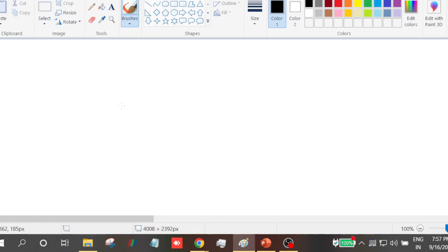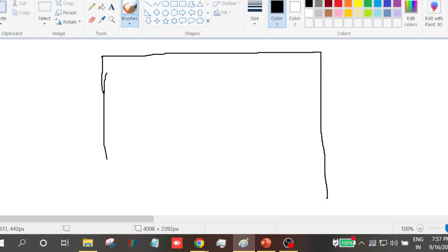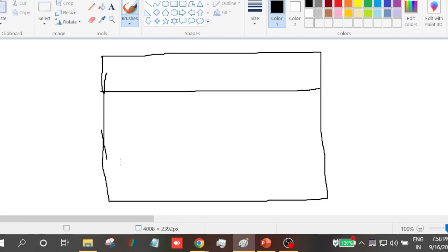So, did you understand the necessity for taking the staggered grid? Because we discussed two problems, right? One with a collocated grid and one with a staggered grid, and saw what was the difference which was happening with respect to the pressure gradient. So, once you understand the necessity, you can understand the staggered grid in a much better form. Okay. So, what we have is this whole domain. Just for simplicity, I will divide it into 3 cross 3 control volumes.